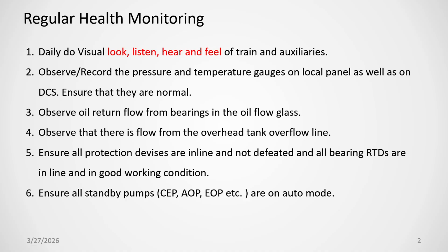Observe the flow from the overhead tank. If there is any power failure on the turbine and the AOP, UOP do not start, then at least the overhead tank should supply flow during the coast down time, a minimum of 45 or 50 minutes, between the bearings, so that the bearing and casing will not touch each other and no bow takes place.